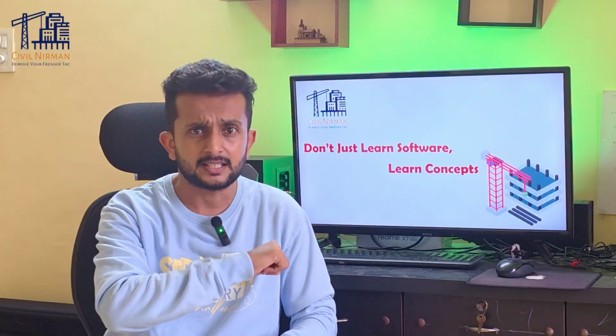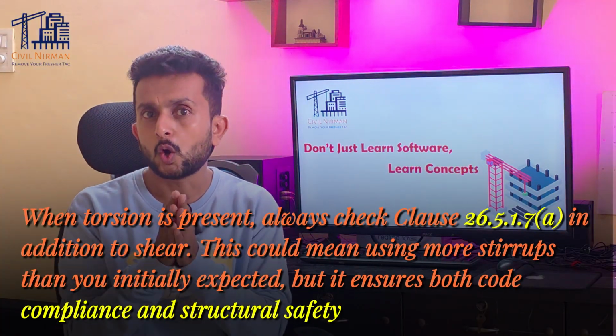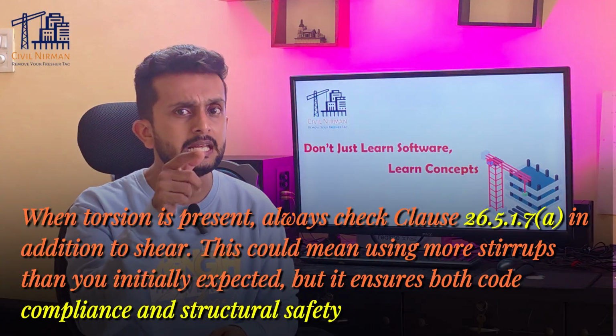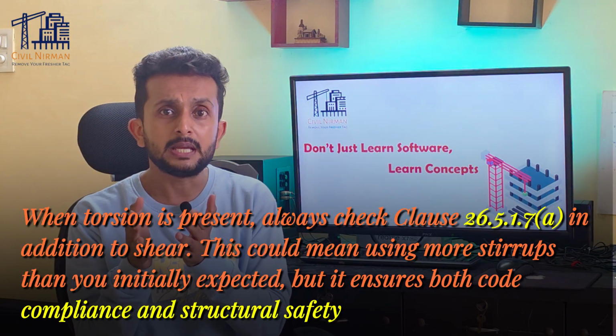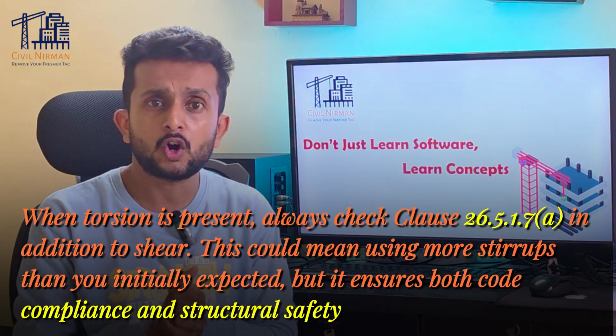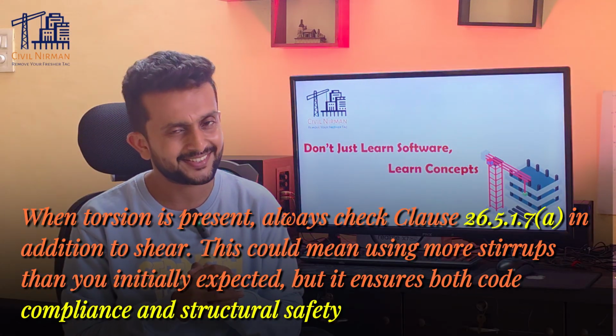So here is the lesson. See, when torsion is present, always check this particular clause 26.5.1.7 in addition to shear. This could mean using more stirrups than you initially expected, but it ensures both code compliance and structural safety.